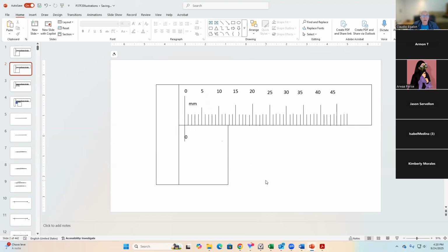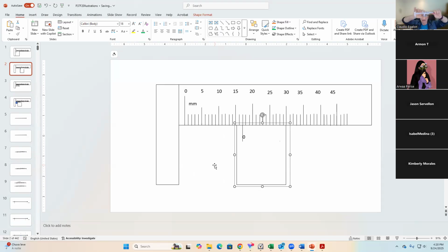So in order to make a measurement with the vernier caliper, we have to open those two jaws, just like I did here, right? And fit my object. Let's say I want to get the diameter of this laser pen. I clamp it, okay? I clamp it, and did I do well? Let's see. Yeah. And just take a reading.